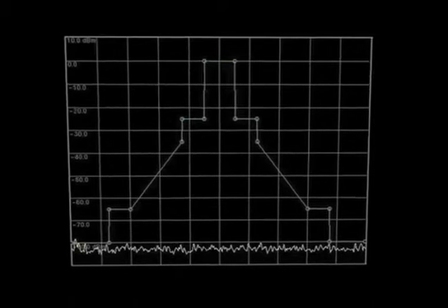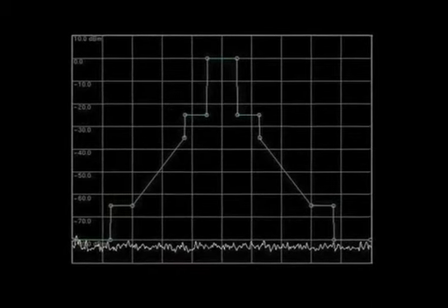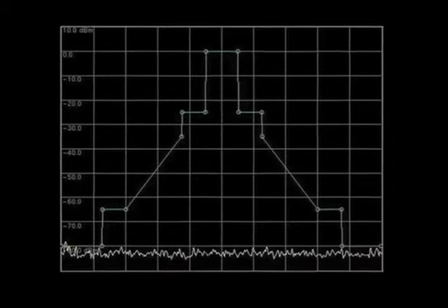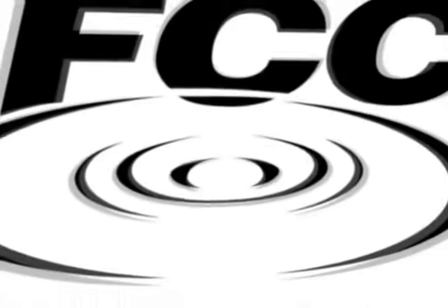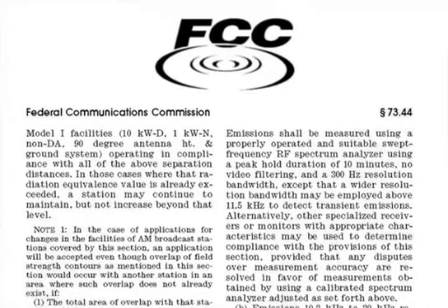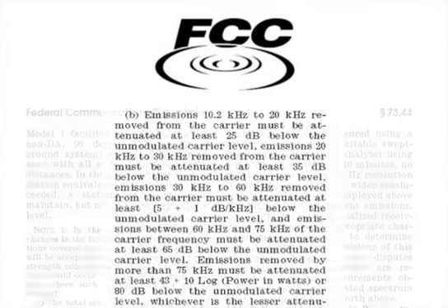On a spectrum analyzer display, limit lines are frequently used to show the expected shape of a modulated signal. Most signal standard documents contain information about the shape of the over-the-air signal in the form of a mask definition.